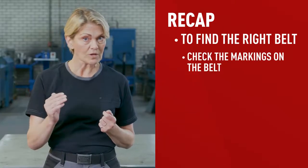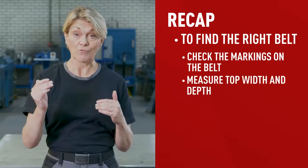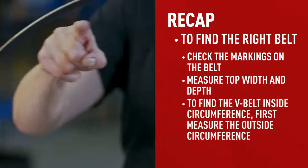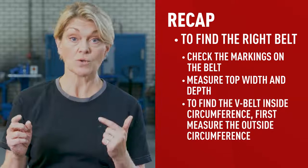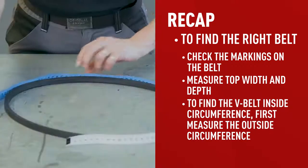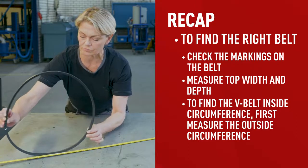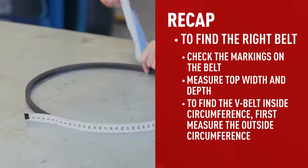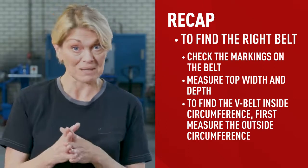If you can't read those, you measure the top width and the depth to determine the profile type. To find the V-belt inner circumference, you first need to measure the outer circumference using one of 3 techniques: with a soft tape measure, a piece of string, or by rolling the belt next to a stiff tape measure. Finally, you subtract a few inches depending on the belt type, like I explained before.